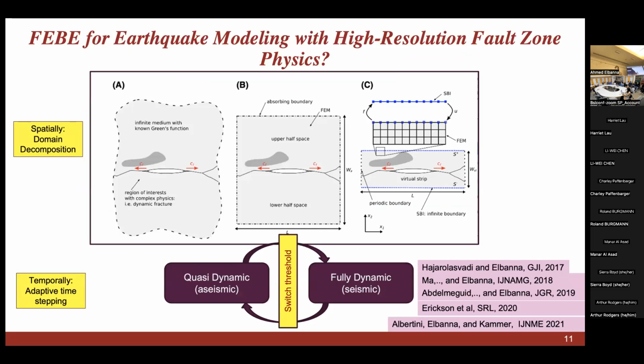So for this specific class of complex problems, we developed a specific numerical scheme we call Phoebe. And Phoebe is just a combination of finite element and spectral boundary integral approach. So usually, when we have nonlinear problems, we will probably start building a finite element model. So we simulate a large enough domain and discretize it with finite elements and then impose on the boundary some sort of absorbing boundary condition to let the waves come out of the system.